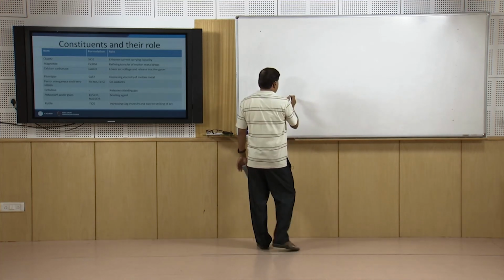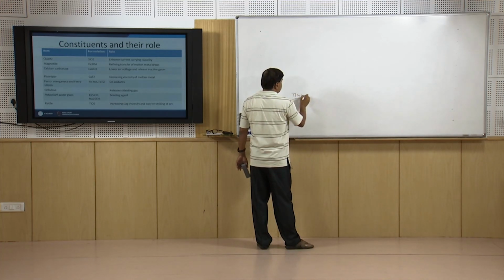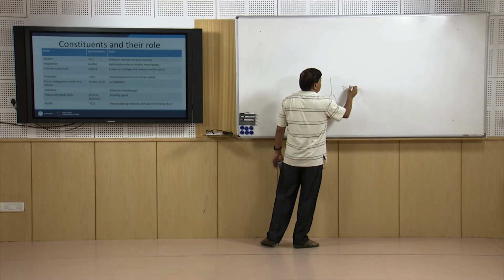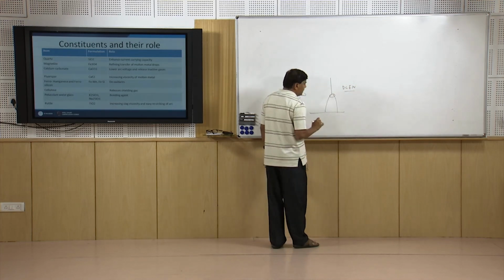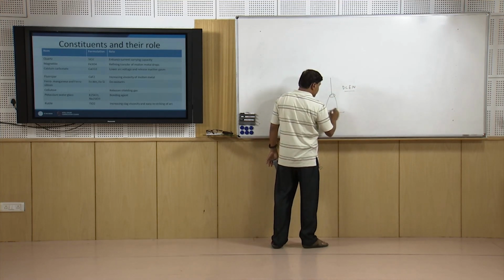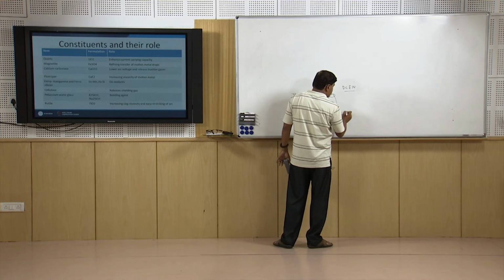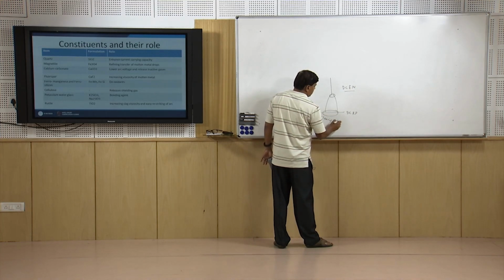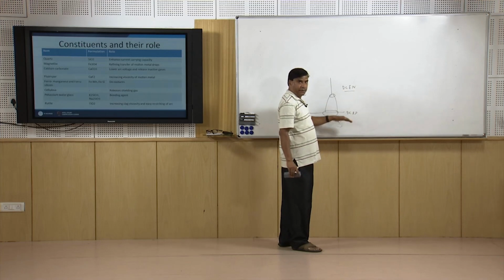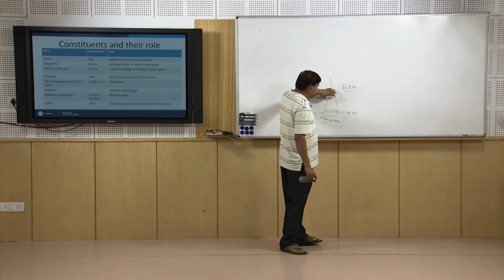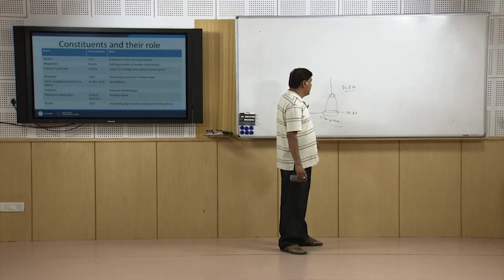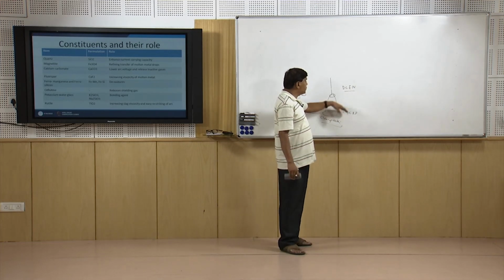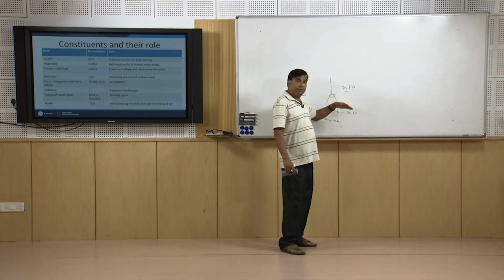If we see the process like TIG welding or GTAW, the use of straight DCEN polarity produces less heat in the electrode and more heat in the workpiece side, while if DCRP is used, we get much better cleaning action. So these are two contradicting requirements. We want less heat generated in any case for much better life of the electrode. At the same time, when aluminum and magnesium are welded, the cleaning action is also wanted, but these two can be achieved using two different types of polarities.